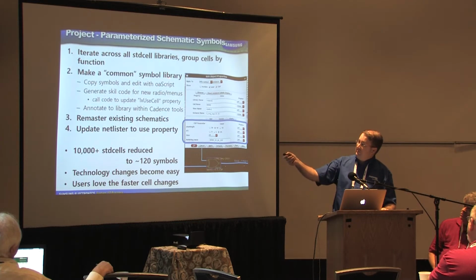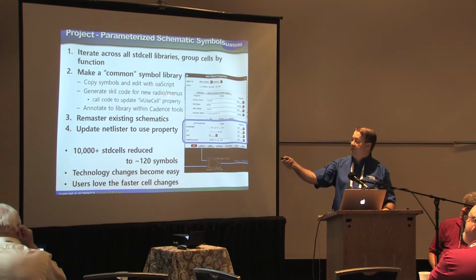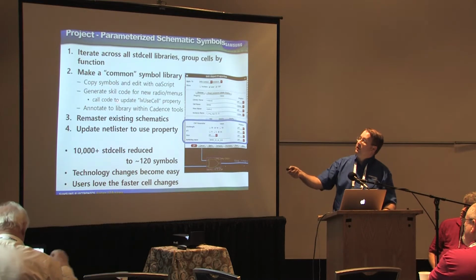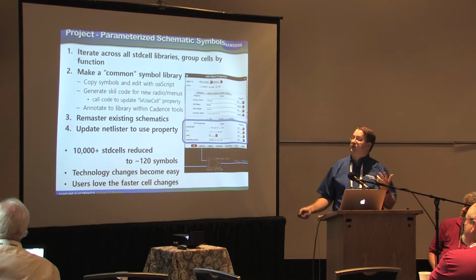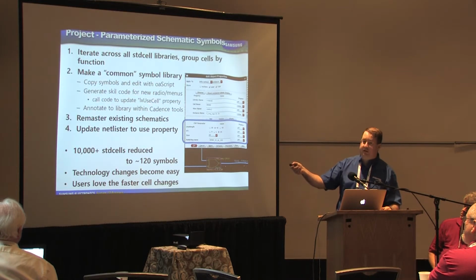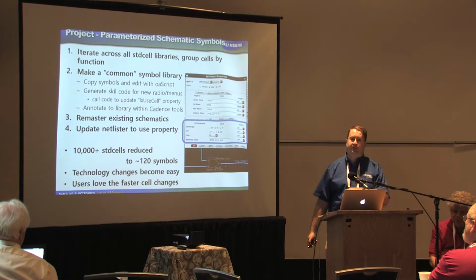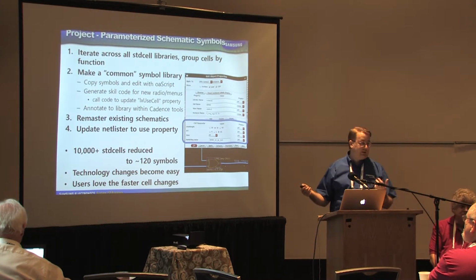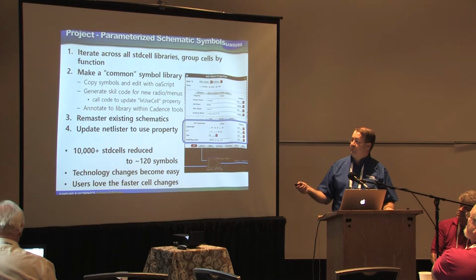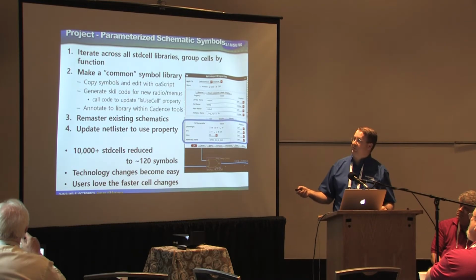So the other thing is you copy and you basically create a simple version of that cell. You add another property that's shown on the cell, and then you generate a lot of SKILL code. And also, if you use Cadence, if you write in this LXU cell property, that will actually automatically work with their layout conversion process. But we were just netlisting out, and so you actually had to get the netlist updater to read that property and use that as a cell name instead.